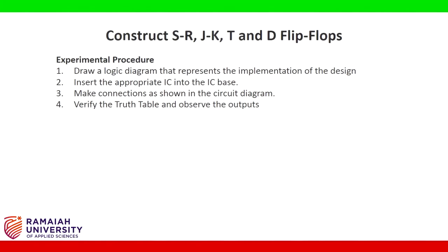Procedure for verification of flip-flop functionalities. Draw a logic diagram that represents the implementation of the design. Insert the appropriate IC into the IC base. Make connections as shown in the circuit diagram. Verify the truth table and observe the outputs.